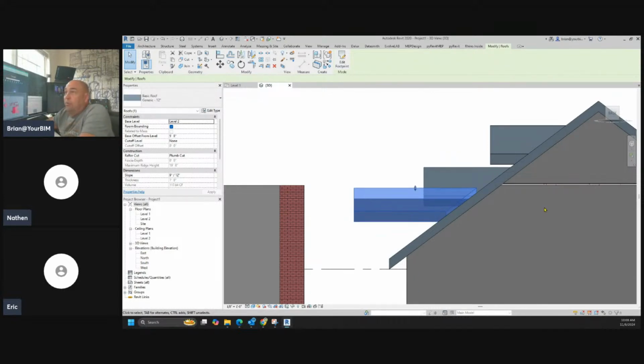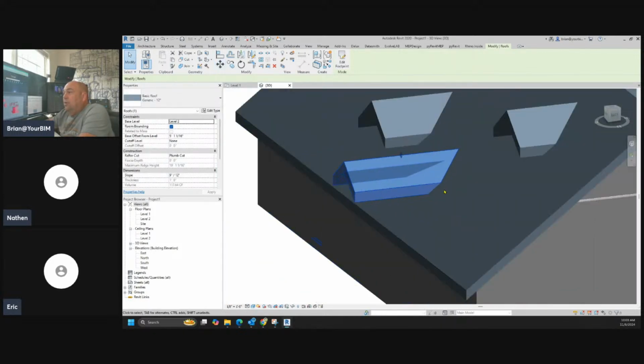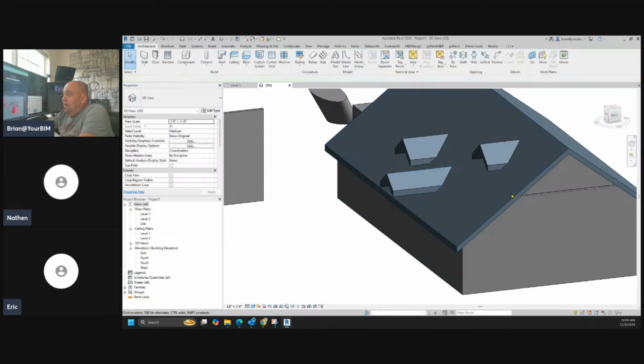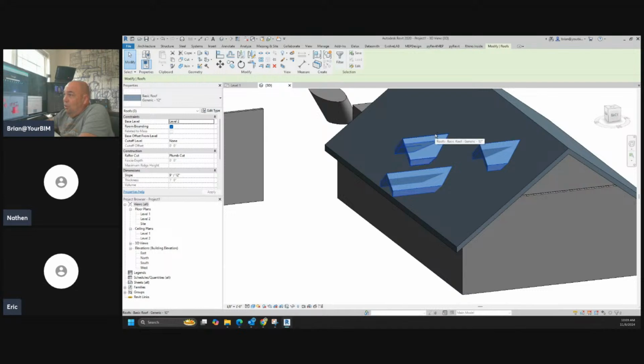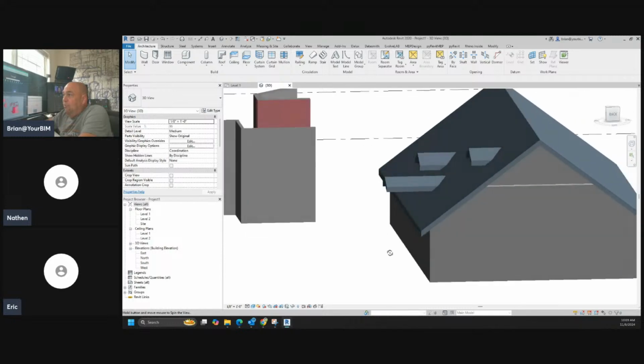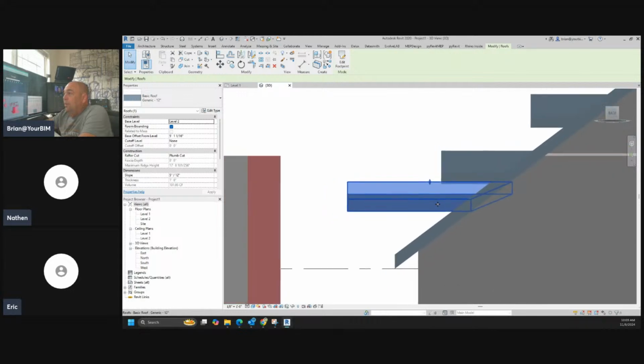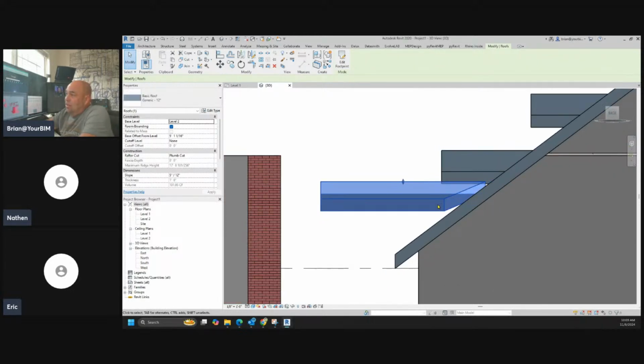Now you can do that, okay? So I could come in here and I could do a move and I could pick this point and come down to pick that point right there, and it would appear the same, okay? The problem is, if I took these three guys, the two that they have that are joined and automatic, as well as mine, and I change the pitch, what happens is that 45 would no longer be a 45, and mine just came away from the roof. Or actually, you can see it went into the roof, because what happens is my angle's not cut correctly.